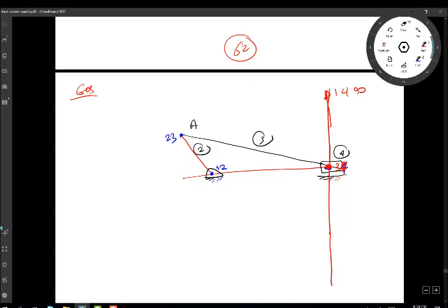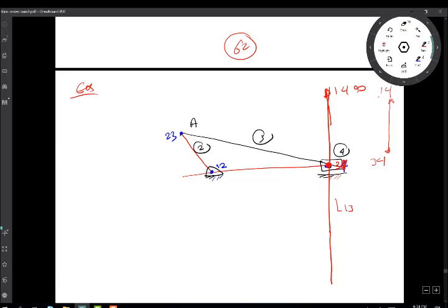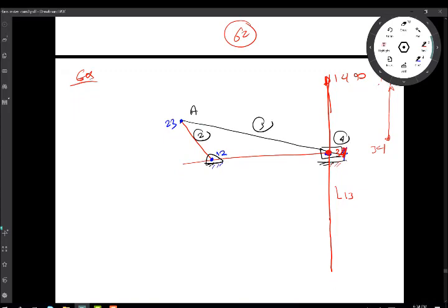If this is 3, 4, and this is 1, 4, you see the common number is 4. The missing point is 1, 3. So this has to be a locus for 1, 3. So this is like the pole of link number 3 should fall on this line. What is the other? I need to find another locus for 1, 3.